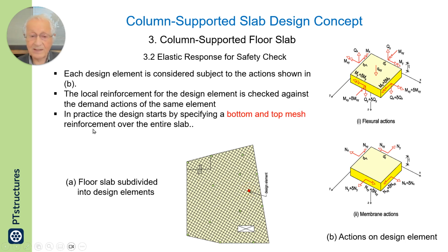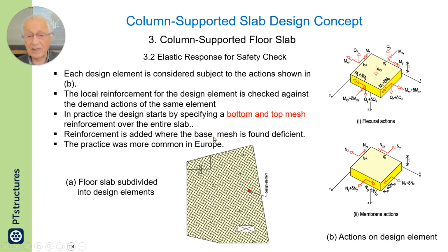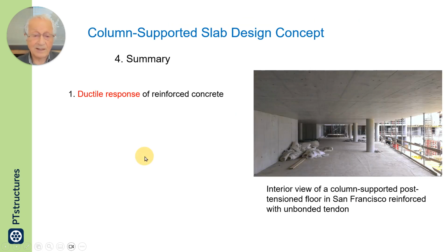In practice, the design starts by specifying bottom and top mesh over the entire slab. Reinforcement is added where the base mesh is deficient. The practice was more common in Europe and less common now. That brings me to the end of this presentation.